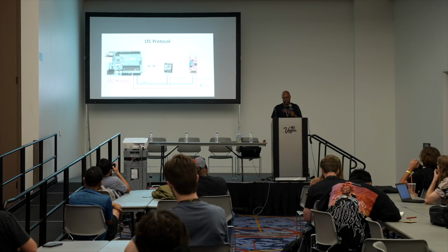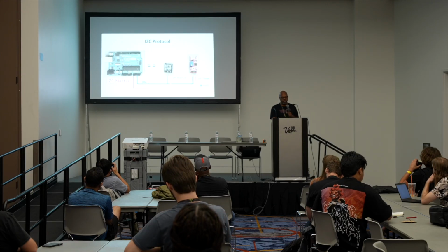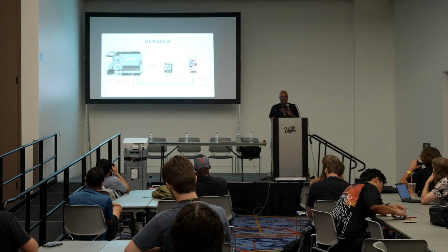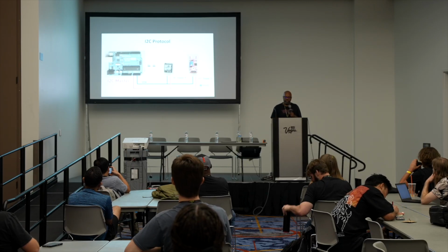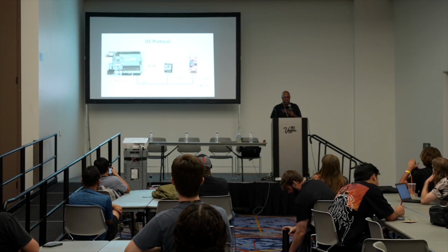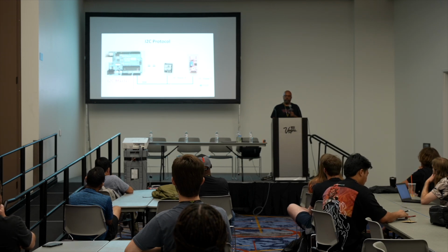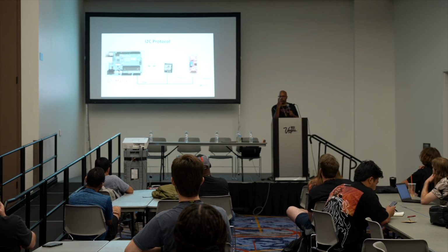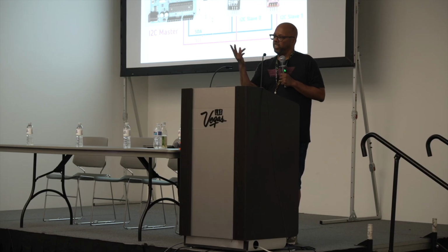Say I've got this Arduino, and I only connected two components that I bought off of Adafruit or whatever, right? And these two components I know are I2C compatible. So when you look at the data sheet for these guys, it'll say, oh, this speaks I2C, this speaks I2C. So then you say, okay, I'm going to use I2C. So you wire it to the I2C pins of your Arduino. SDA and SCL are the two pins for I2C. SDA is a data line, SCL is a clock, right?